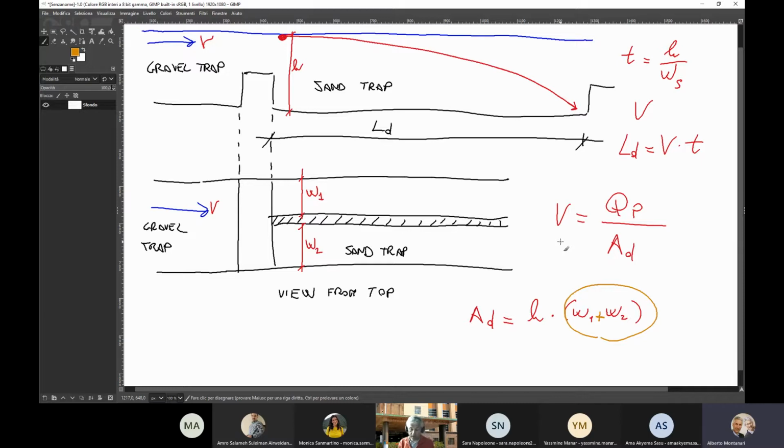If the river is very constrained by the slopes, then you have to limit the width because you don't want to excavate at the foot of the slopes. So you guess W1 and W2, and what are usual values? Of course, it is variable, and it may range from something like 3 meters to even 15 meters if you have important withdrawals with a lot of room in the sides.